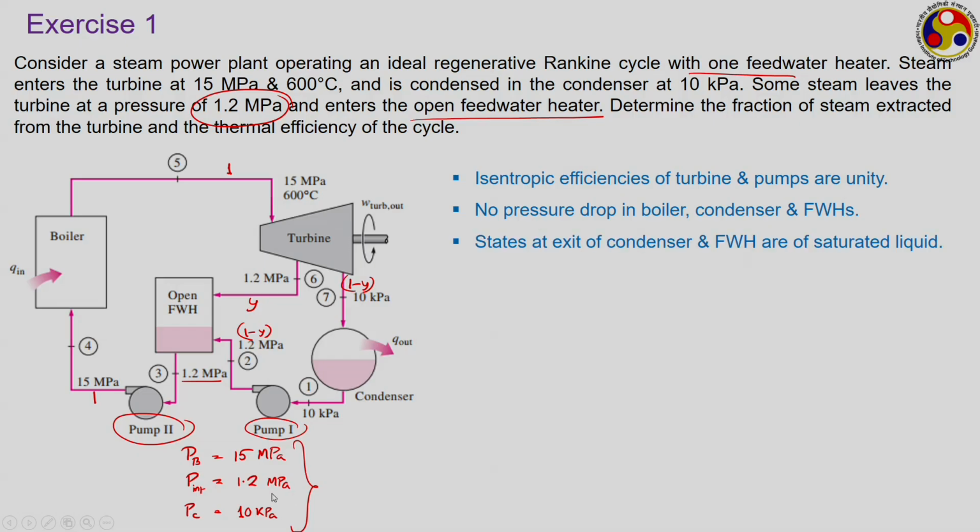Also, the states at the exit of the condenser and feed water heater are saturated liquid. That is important, and it is associated only with the ideal cycle. In a practical cycle they may be subcooled or they may be a very low quality mixture as well. So, we have to work out the states.